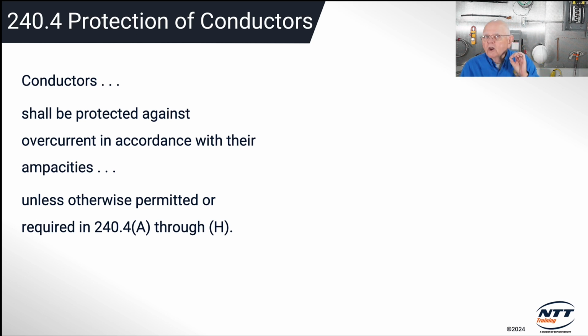So if all the way up to the terminals or inside of the motor in that hermetic compressor, or the fan unit for that matter, for any reason I have a short circuit or a ground fault, I'm protected by that upstream breaker. Even if it's a 35 amp breaker in this case. That 35 amp breaker under short circuit or ground fault is going to trip instantaneously, no matter the size wire that's supplying my branch circuit.